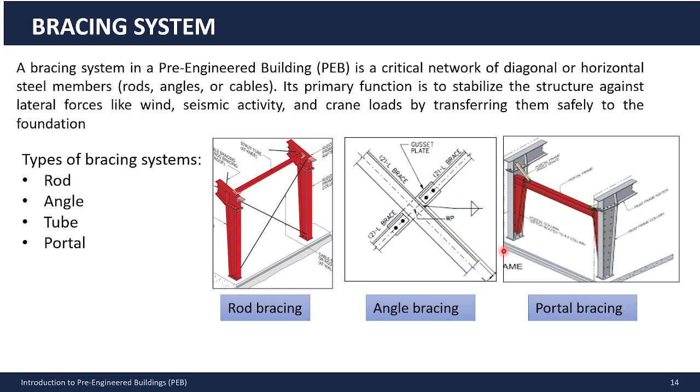The bracing system is what keeps the PEB stable under lateral loads: wind, seismic and crane forces. Mostly these will cause lateral loads. The bracing transfers these forces safely to the foundations.